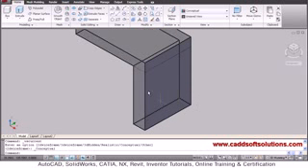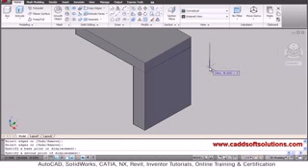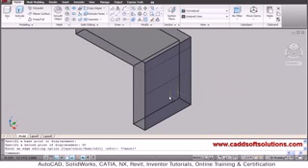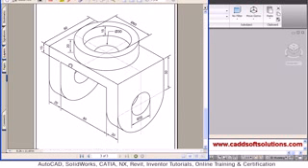Now here a circle is there at a distance of 50 from the top. So we will just copy this edge, enter base point direction. So at the bottom we have to go by a distance of 50. Okay, the height is not correct, so we have to reduce this by 15 actually.